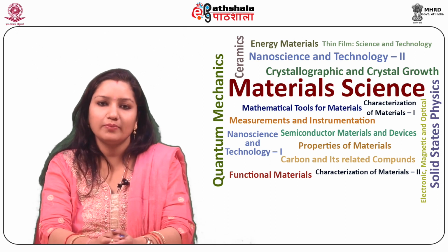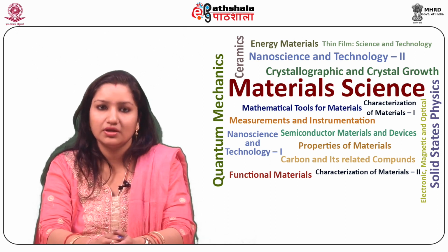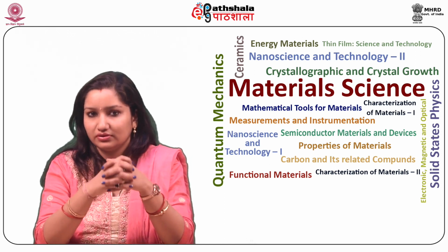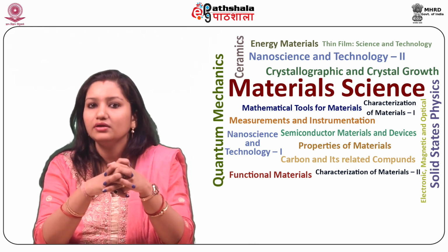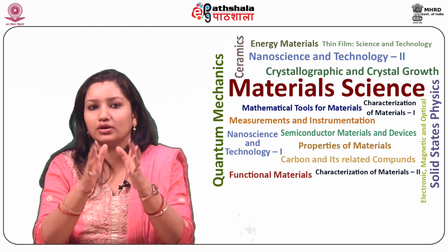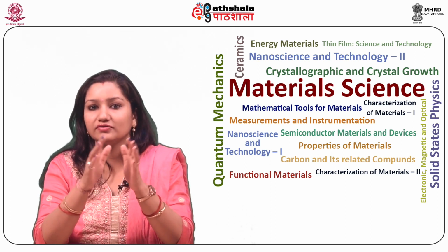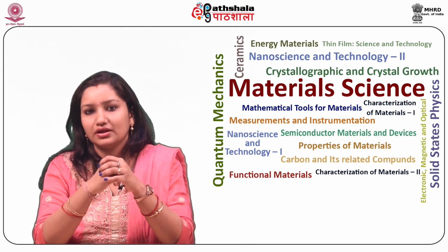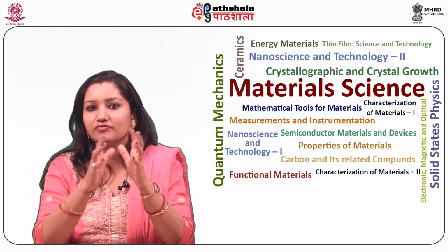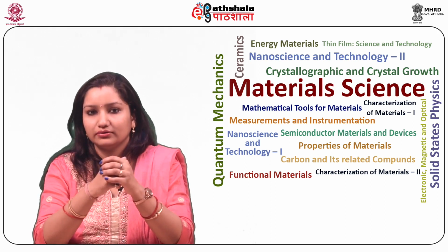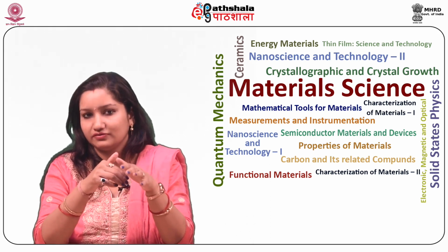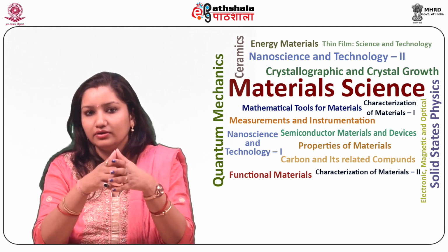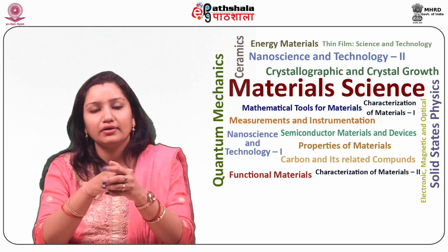The next type of thin film solar cell is the cadmium telluride, that is CdTe, solar cell. Cadmium telluride is the only thin film solar panel technology that has surpassed the cost efficiency of crystalline silicon solar panels in a significant proportion of the market, that is multi-kilowatt systems. The efficiency of solar panels based on cadmium telluride usually operates in the range of 9 to 11%.